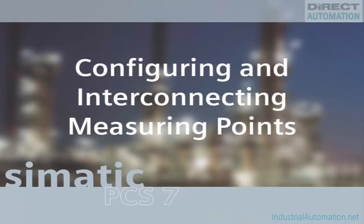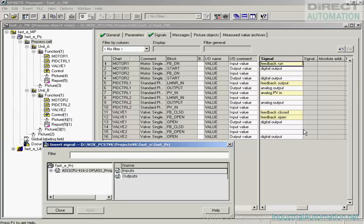In this sequence, we are going to show you how you can easily assign I/O signals to the individual charts and function blocks that are used in the application. We will use the symbolical names which have been defined previously, and assign them to the corresponding measuring points. The signals are interfaced easily and conveniently in the Process Object view. In this view, it is possible to carry out all assignments globally, without having to open up each individual chart or function block one by one.